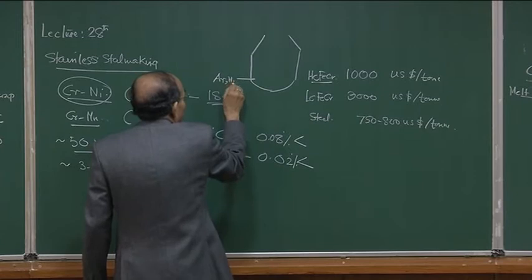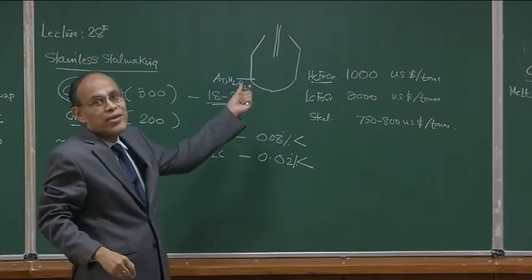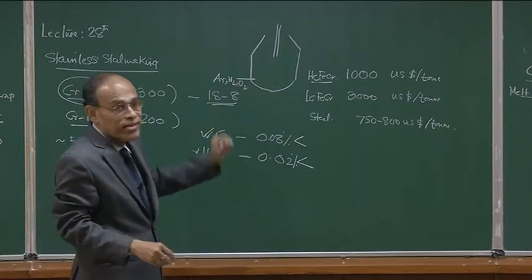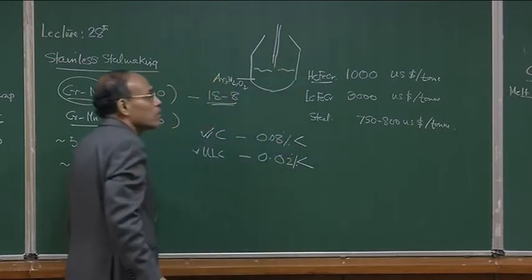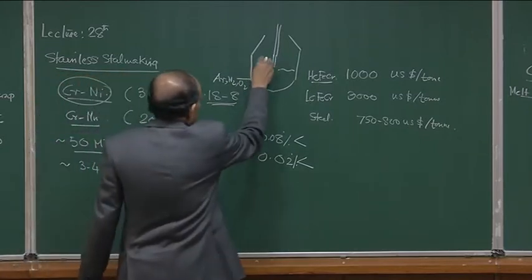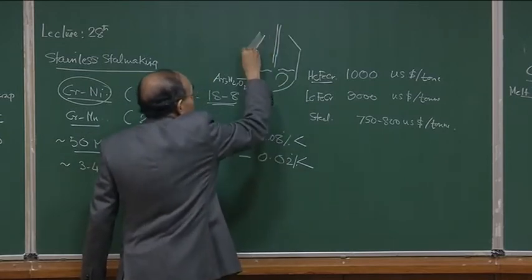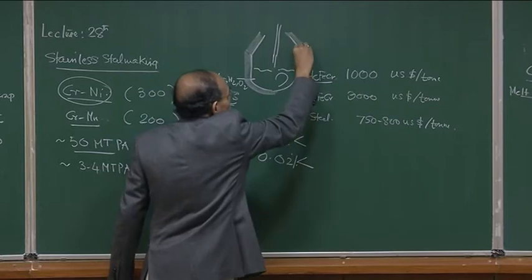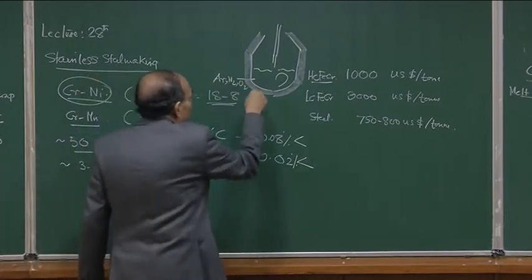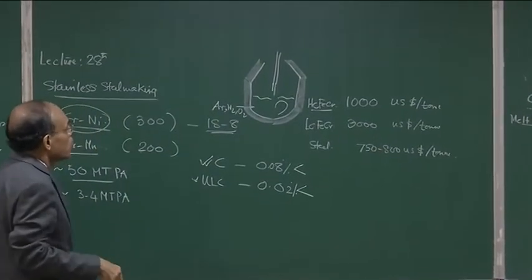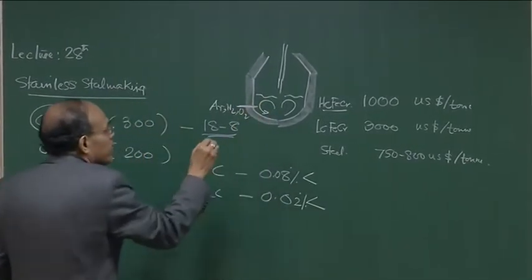It has argon, nitrogen, oxygen, and you have a top lance here, and this lance does not blow at the same rate as a basic oxygen converter. There is no supersonic jet here, and we know that oxygen transfer is very, very poor from the top, in the absence of an emulsion phase. So, this side blowing facility basically helps to provide the stirring in the system.